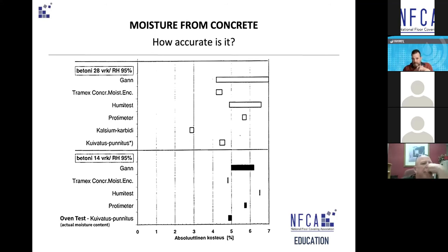What's interesting about the calcium carbide, just so people know, is that you mentioned, Chris, in the introduction that there's two types of moisture. There's vapor and there is liquid moisture. But there's actually, and this is something Bob and I were discussing recently, three types of moisture, because there's absorbed and adsorbed moisture. So concrete has moisture within it, which is known as absorbed moisture. And then it has moisture that's attached to the aggregate, and that's adsorbed. It's like droplets on the outside of an aggregate.